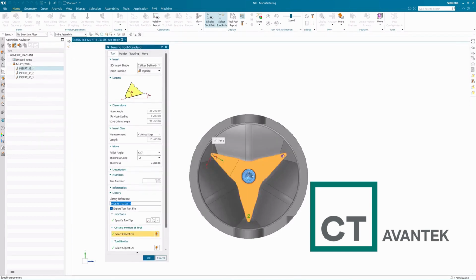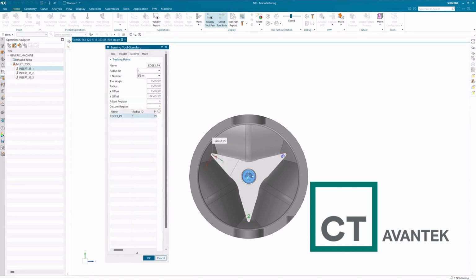Now let's define and set up the first insert. First, make sure Export Tool Part File is toggled on. Define the ISO insert shape. Specify correct values for nose angle and radius. Specify the orient angle. This I will show how to measure later. Optionally, set a library reference. We can now also specify the cutting portion of the tool and the tool holder.